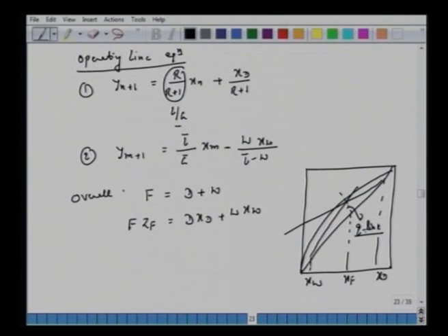Okay, so now in our case, when there is no reboiler and we have direct steam, the bottom product L bar is nothing but our product W. This is G bar here, which is nothing but the steam flow rate. How can we modify this approach and do the same calculation we were doing earlier?